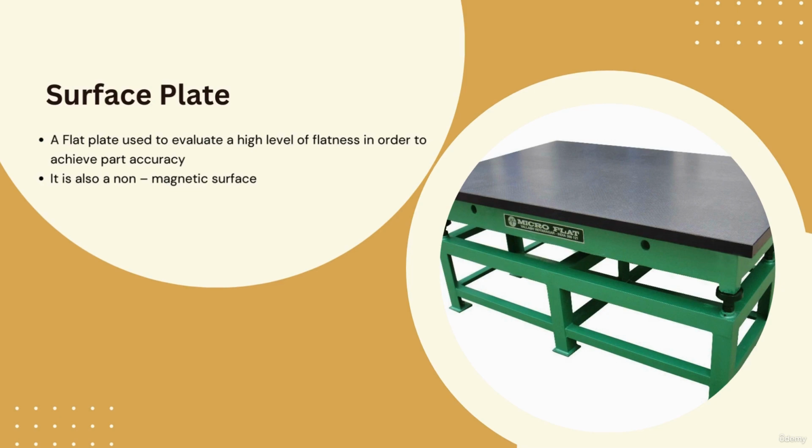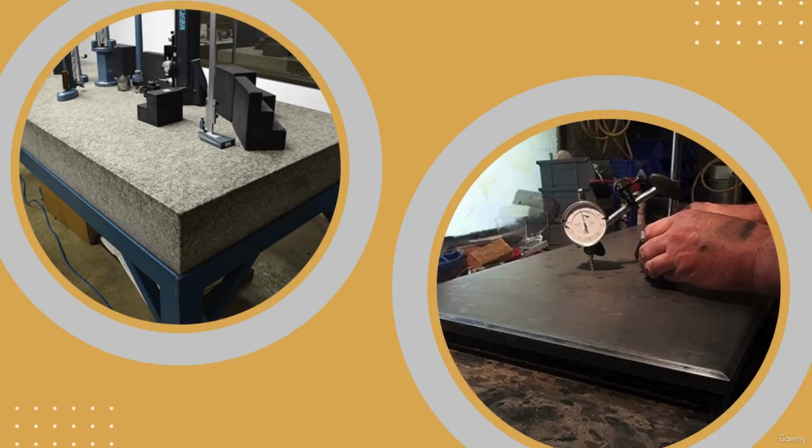This component helps to measure the overall part without any deviations, because it is only applicable for flat parts. Place the part on the face and use a dial gauge or height gauge. You can measure your components for the difference in flatness. That is the exact use of this surface plate in our industries.